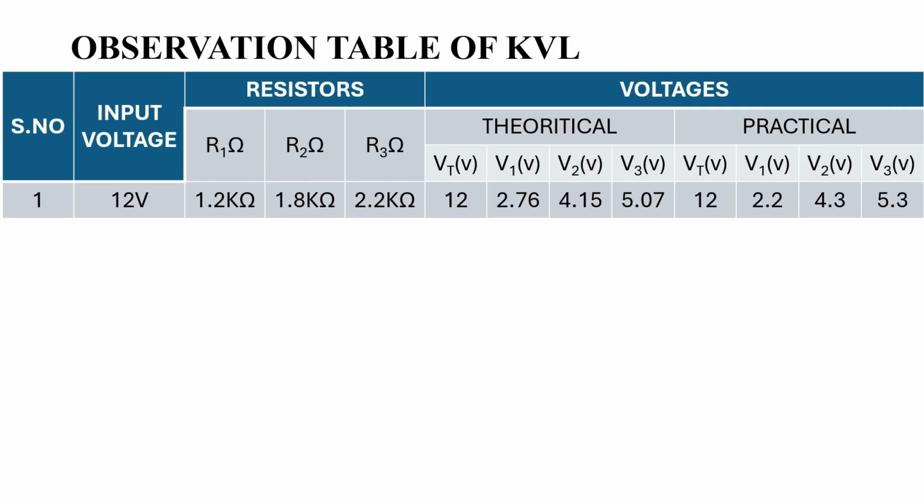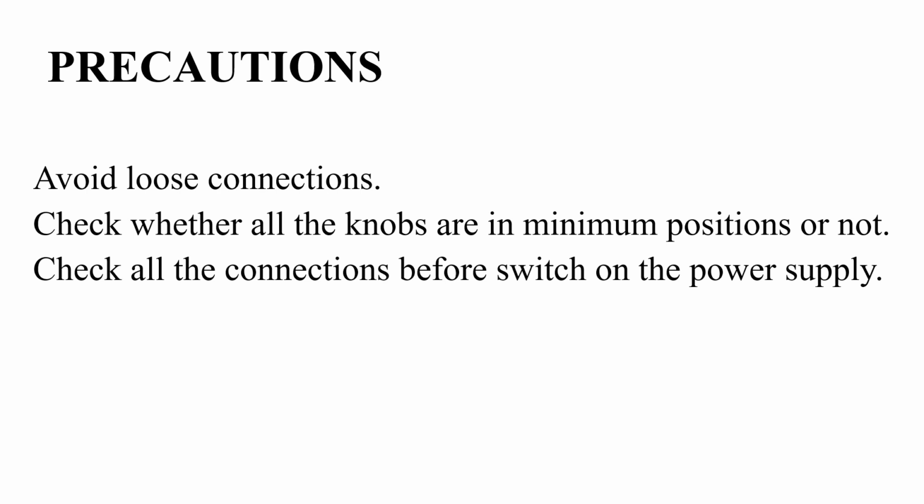Now note down these values in the table. Precautions: avoid loose connections. Check whether all knobs are in minimum position or not. Check all the connections before switching on the power supply.